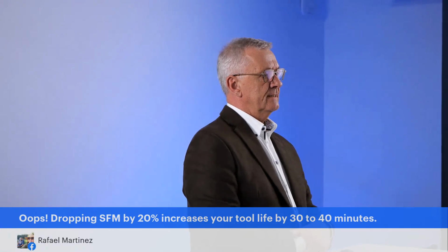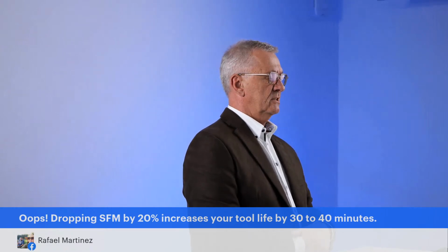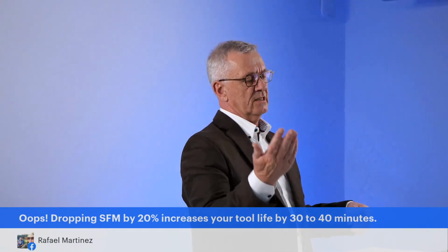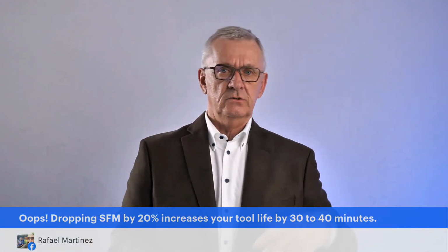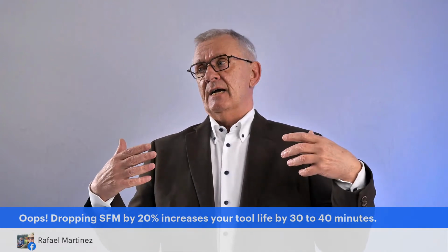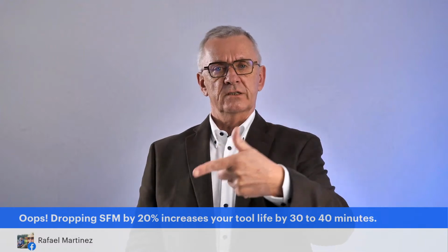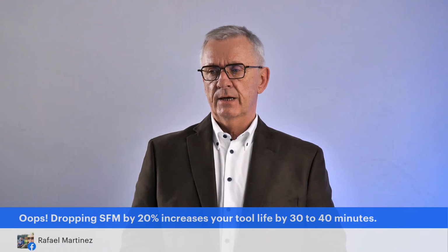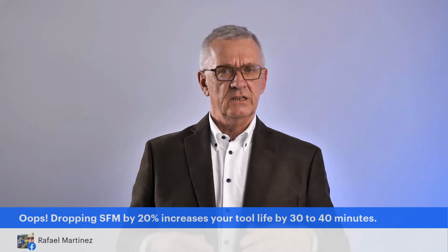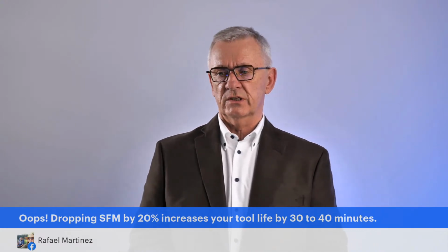It's knowing the consequences of what you do, because you change the carbide grade, you change the geometry, you change the nose radius, you change the cutting speed, you change the feed. One, you need to know why you change this, and two, you need to know what are the consequences of the change you do. Obviously. That type of relations are so important to have full insight when you are in the 4th or the 5th phase of a selection process.